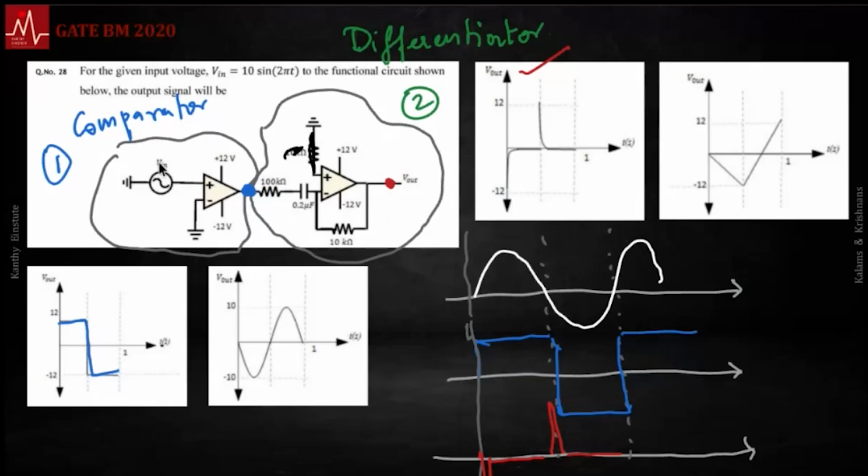Notice, is it an inverting amplifier? No, there is no inverting amplifier with gain one involved. So this is totally out of the circuit, it is not given there. Even if it were an integrator, notice if you integrate this blue curve, and the integrator is again through the negative input terminal, it becomes thus, and technically it should get back here. So perhaps this option is not really an integrator.